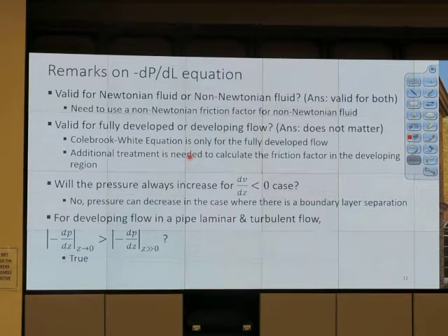What about emulsion? Is that shear thinning or shear thickening? So the way I look at this is this. If we have very tiny, very fine droplets, many droplets, that causes more surface. So when they move, they may rub against each other. Let's think about the extreme case. If you have just one droplet of oil in water, that's not viscous, right? But if I have the same volume but multiple droplets, millions of them, very fine, it is more viscous.